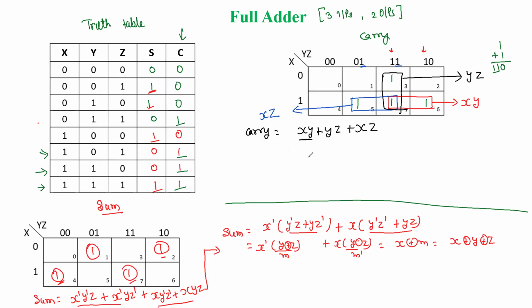So initially this xy we will keep as it is, since xy is already there in the previous situation also. Now the remaining yz and xz we are going to change so that each term will have all literals. For that you know that if you have a plus a dash, that value is 1. So like this, complement plus that number will multiply here. That value is 1, so it is not going to make any change.